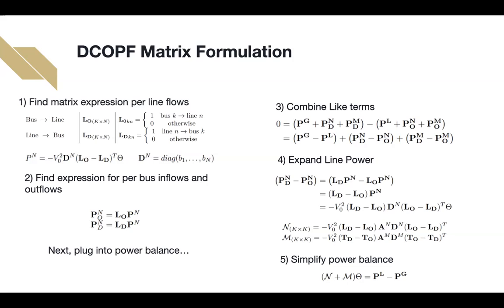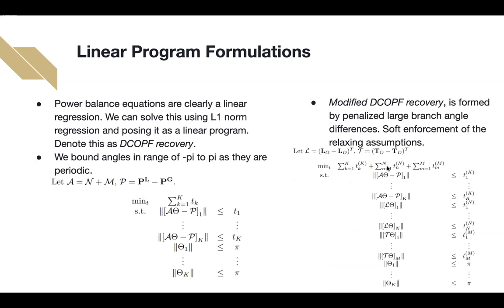And so then we can simplify our original power balance equations by moving our load and generation, which we are given, over to the right-hand side, and then simplifying our line and transformer powers into this expression you can see here. And so moving forward, we put this into a linear program.